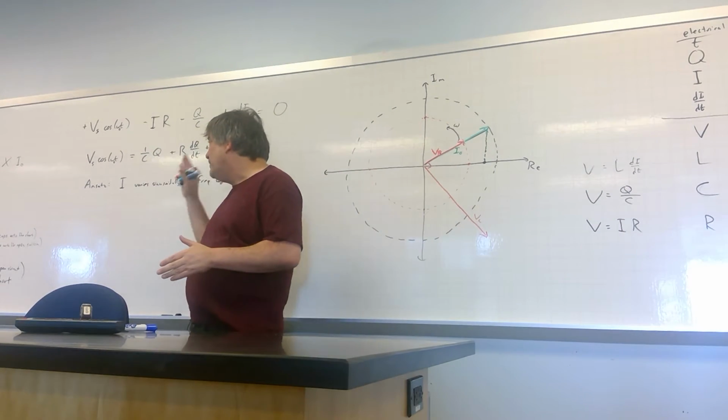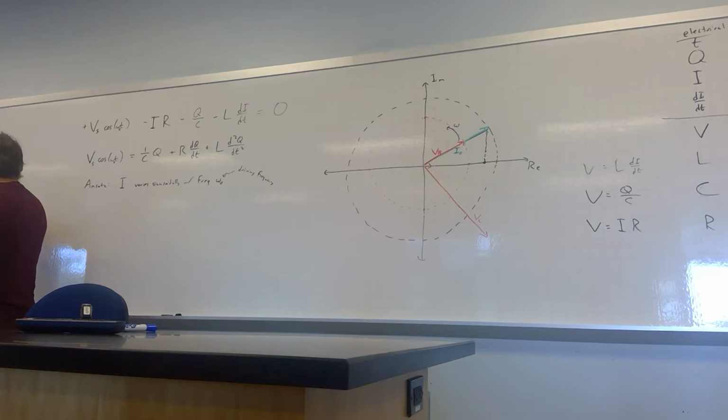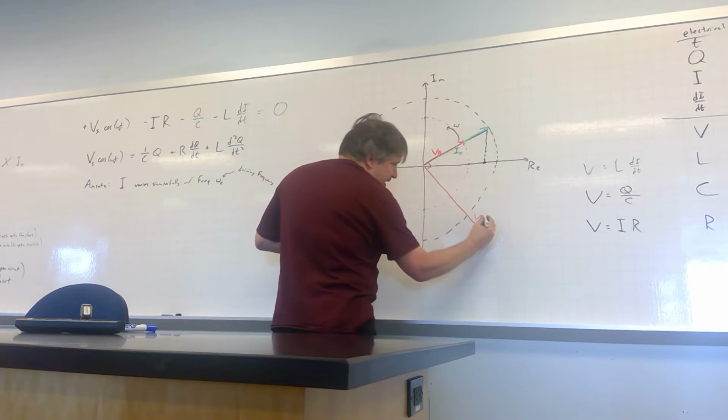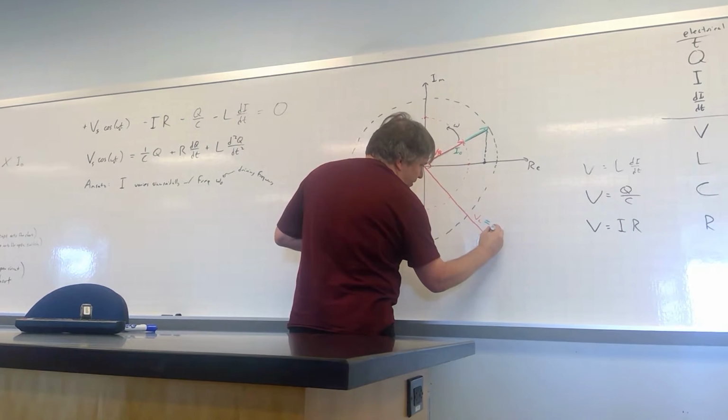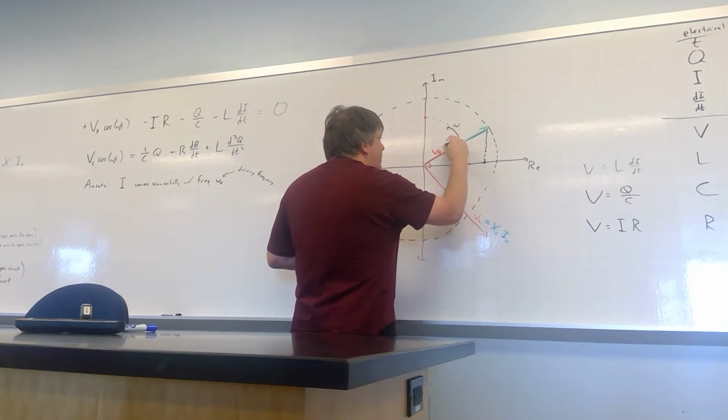You would actually measure the impedance of each of the three devices, and the devices with larger impedance, oh, I'm sorry, the impedance of the capacitor would have to be larger than the resistor, I'm sorry. The devices with larger impedance would get a bigger voltage drop for that same current. All right, so there's my voltage across the capacitor, and the way I have calculated its value is I took the impedance of the capacitor times the current. The way I calculated this value was I took the resistor times the current.